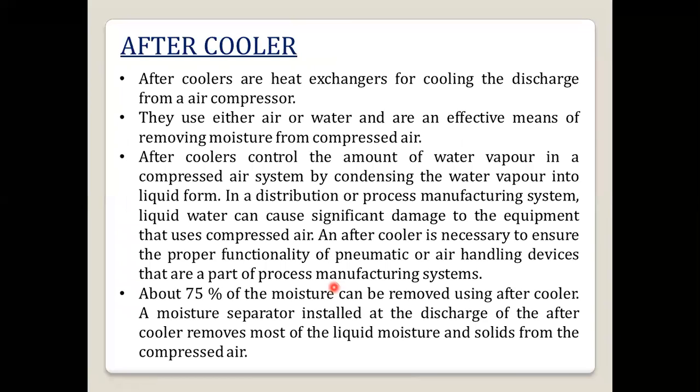So now we will start the topic of the after cooler. After coolers are heat exchangers for cooling the discharge from an air compressor. An after cooler is nothing but a heat exchanger. They use either water or air. They are an effective means of removing the moisture from the compressed air. After coolers control the amount of water vapor in the compressed air system by condensing the water vapor into liquid form.